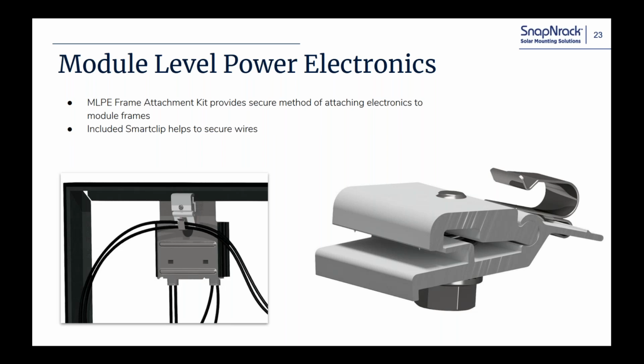With a railless system, you're going to be doing the same kind of thing on the ground. You're going to prep all these out and get them ready to go so that the guys can just bring them up onto the roof, lower them in place, and then just attach the mounts and then clip the modules together. Just clip those MC4s right together with the tension already ready to go, because everything's been prepped out on the ground.